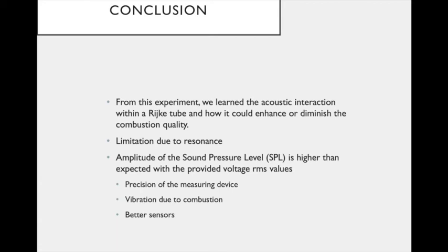But with this much benefit from resonance, we also see limitations, because if we try to apply resonance combustion to current gas turbine engines or rockets, then it could cause some very serious damage because all the moving parts will not be able to withstand the chambers constantly expanding and contracting by a significant margin.